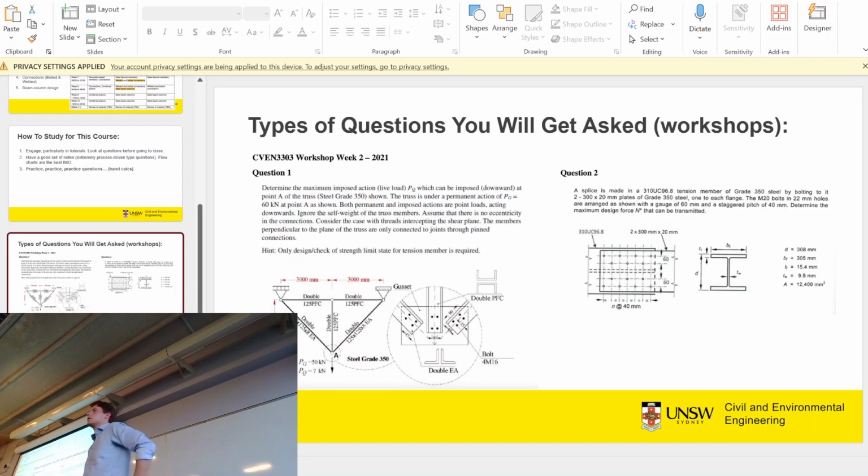So if it's connected horizontally. Yeah, so it's like two members like this, connected horizontally, bolts going through them. How do you think that those two tension members could fail? Isn't it like a failure method? Yeah, failure method, yeah. It would just be shear. Shear of what? Shear of the bolt. Yeah, really good.